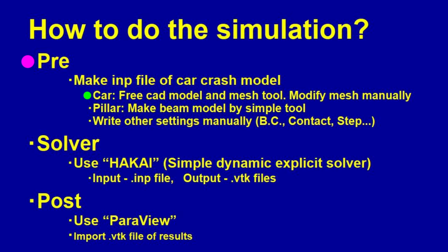As necessary, modifying the mesh manually will be useful for later use in parametric studies. For the pillar, we can model it as a simple rectangular shape with some tools. Then, other settings like boundary conditions, contact, and analysis step size, we can write manually.